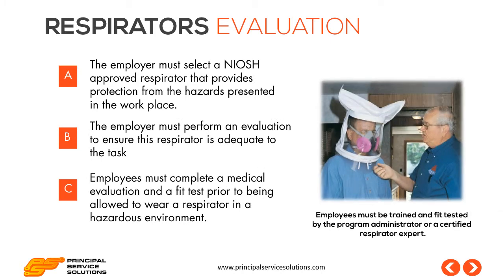The employer must select a NIOSH-approved respirator that provides protection from the hazards presented in the workplace. The employer must perform an evaluation to ensure this respirator is adequate to the task. Employees must complete a medical evaluation and a fit test prior to being allowed to wear a respirator in a hazardous environment.